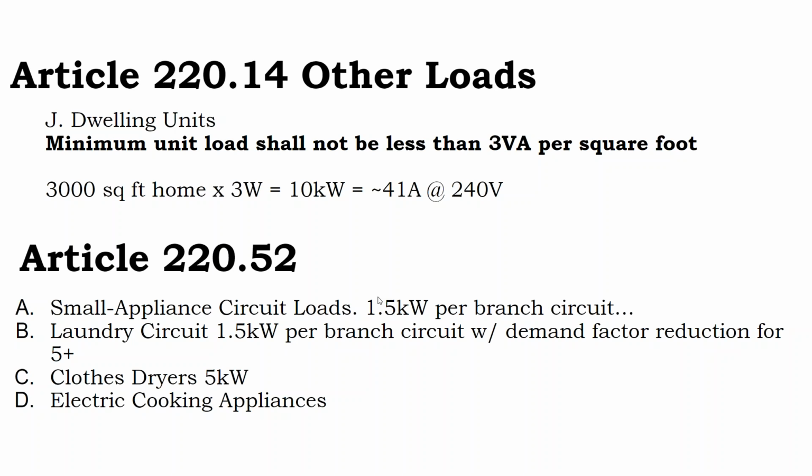If I just do everything perfect and select all of my appliances to keep my home power draw under 3 kilowatts, can I get away with a 3 kilowatt power supply? Can I run a house off a 20 amp circuit? The answer is no. Code requires, pretty much comes out to like 100 amp service at a minimum for dwellings, and then it goes up from there.